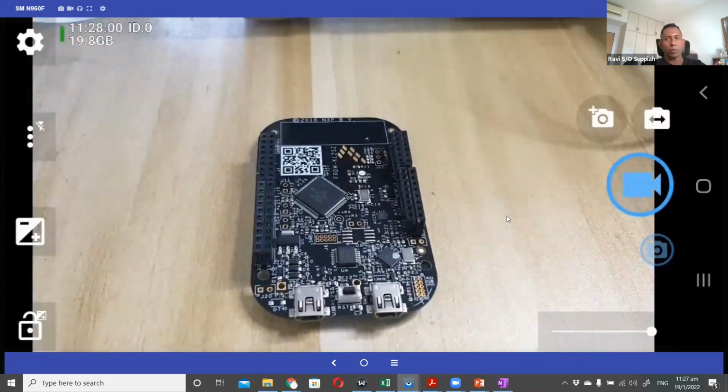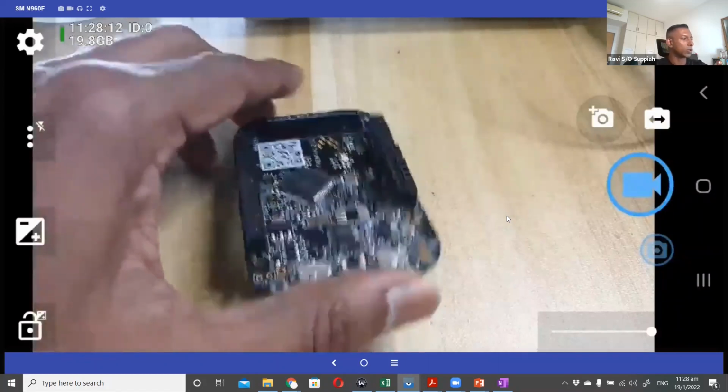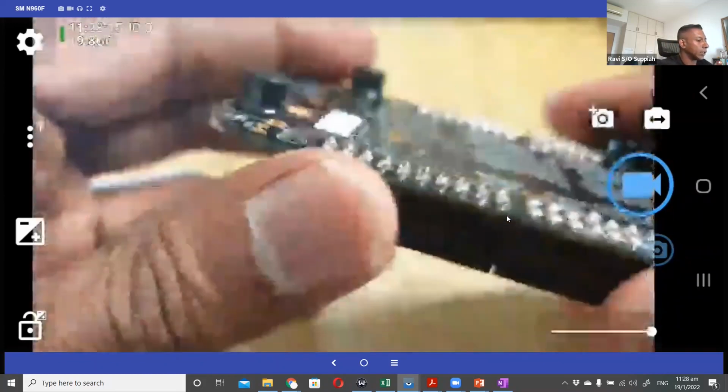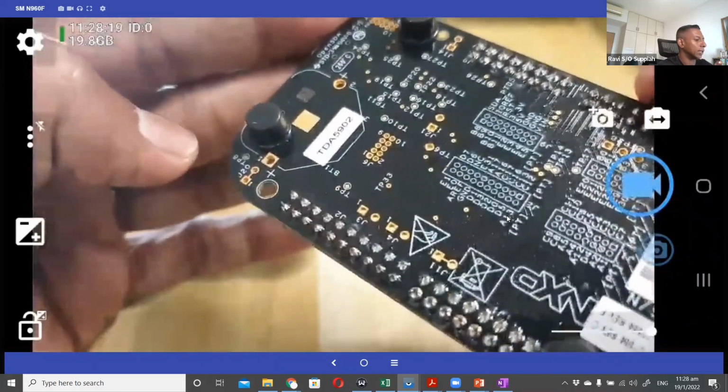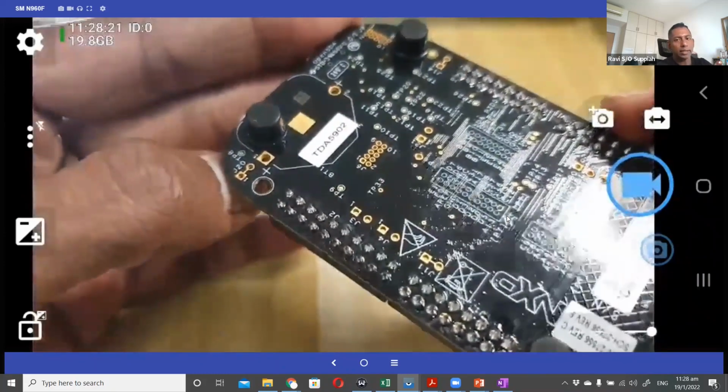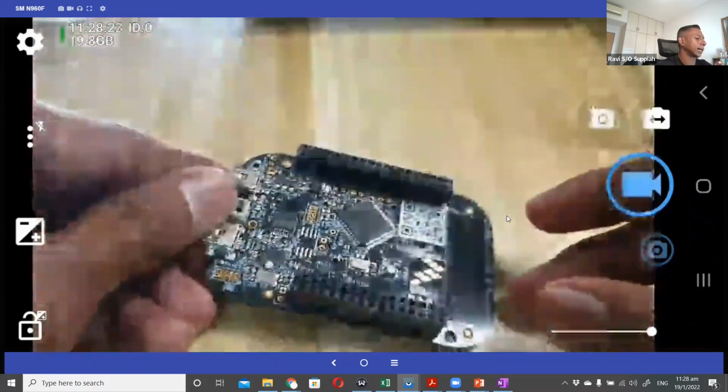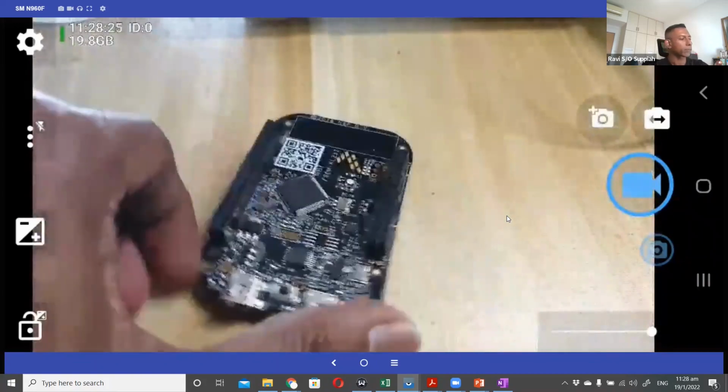As much as I want you all to be good in soldering, you can practice on your own using other spare prototyping boards and things like that. But do not practice on this board, because if you do not solder it properly and create, let's say, a short circuit along the pins over here, you need to desolder and then resolder again, and there's a high chance you might damage the board.